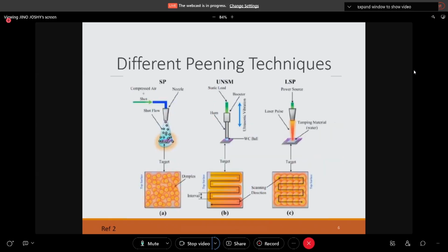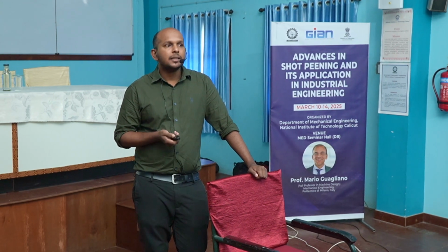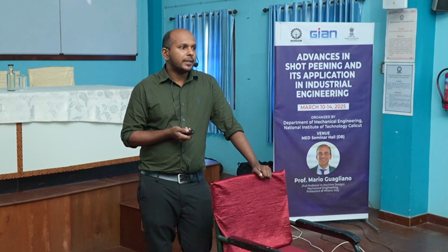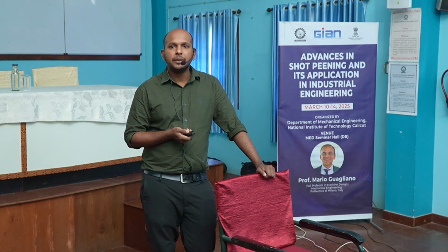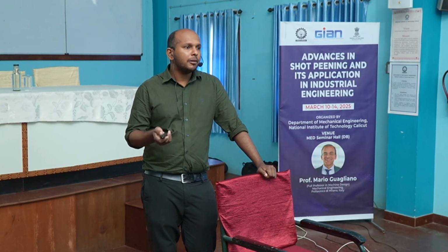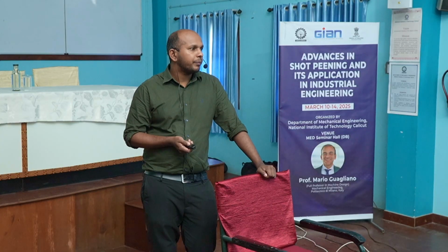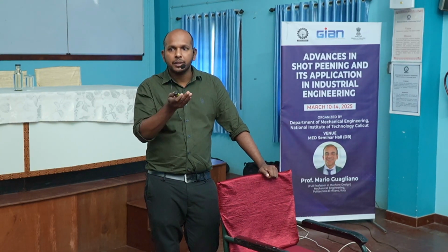Okay, so what is a shot peening process? Professor Mario already discussed what a shot peening process is. What is actually a shot peening process? The basic definition: we have a hard ball, and with this hard ball we impinge on a surface. As the ball impinges on the surface, what happens? There will be some deformation. The surface gets deformed.